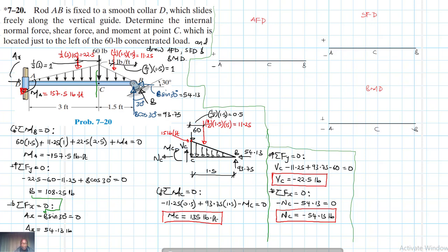ACB. Great. We're using these differential equations. We have the axial force A prime, I'm calling it A prime, that's dA/dx, which is going to be equal to the axial distributed force, I'm calling Q star, and the axial force itself is equal to the area under the axial distributed force. And we have V prime, which is just equal to Q, the lateral distributed force. Q star is the axial distributed force, Q is the lateral, and V itself is just the area under this lateral distributed force. And then we have M prime, which is just equal to V, and M itself is just the area under the shear diagram. So we're going to use those equations.